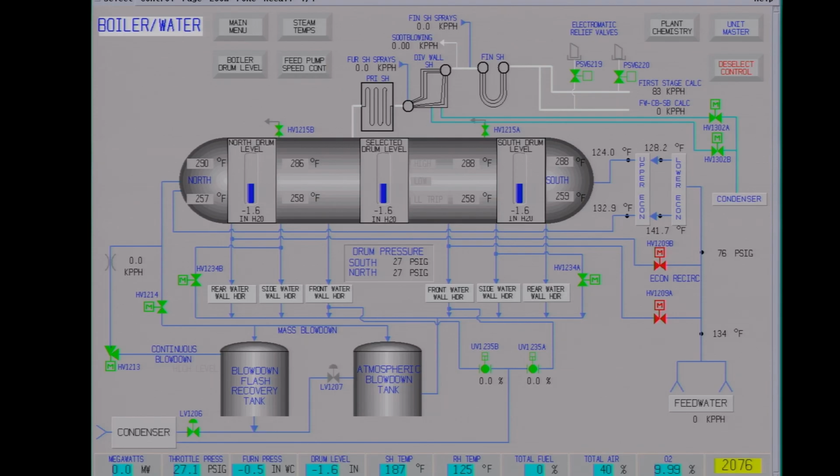Another thing we'll have to do is flush all the drain valves that we opened to drain the boiler. We'll have to open them up a little bit, flush them, and then retighten them. We'll do this at 25 psi and 200 psi. Any leaking water through these valves will destroy them fairly quickly. Plus you lose plant efficiency. There are a lot of drain valves, so it's critical to make sure that they're all seated correctly. If somebody doesn't shut a valve right, it will damage the seat in time.